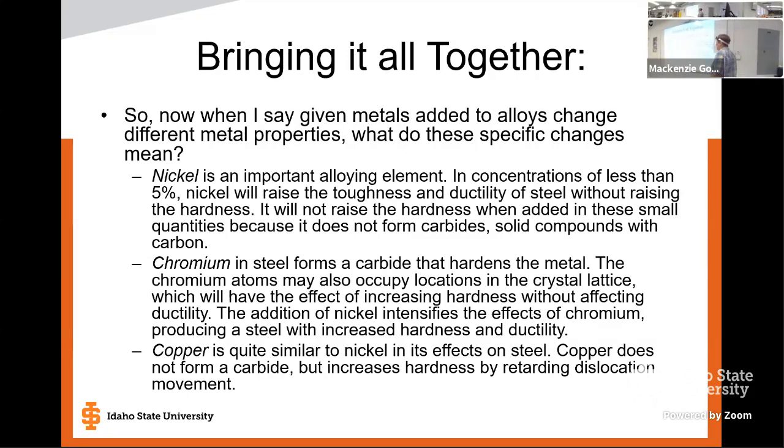Yeah. So if you have the opposite of nickel, right? You've got a pipe that's in a lot of flow, you've got worries about erosion, or Jennifer said that high pressure, you've got a constant force that's constantly pushing out on the metal because you've got a pressurized system. Chromium is a good choice for making our steel alloy good for that application.